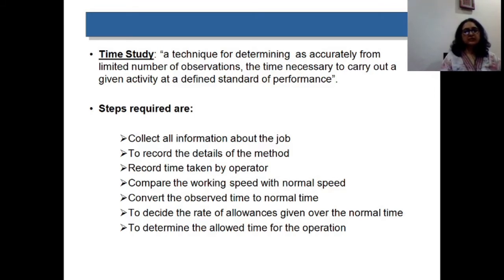First is to collect all the information about the job. Whatever job is taken for study, all the information about the job has to be collected. Secondly, to record the details of the method. For that, the operations are broken down into different elements, and each element is studied and recorded. Then, to record the time taken by the operator.